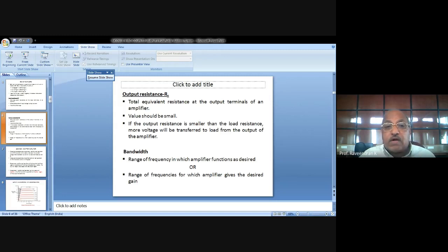That is the main feature of the common emitter amplifier or RC coupled common emitter amplifier. The output voltage will always have a phase inversion or a phase displacement of 180 electrical degrees. Or in other words, the input signal and output signal are in phase opposition. They are going with the same phase, but it is opposite. When it goes to positive, it goes to negative. That is phase opposition. Follow my point? Okay.